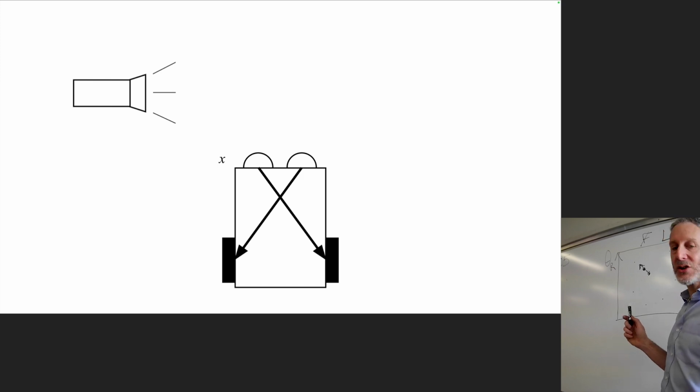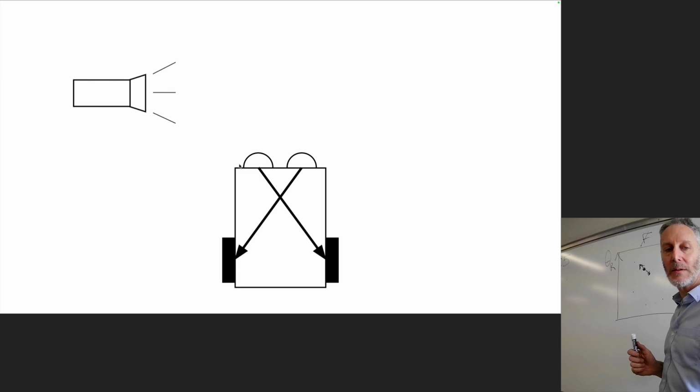Okay, let's imagine in this particular vehicle that we have synaptic weights 1 and 1. Let's assume that we change x. We move the left light sensor a little bit further to the left. How has that changed the behavior of the robot? If this second robot still has the synaptic weights 1 and 1, does this particular robot do a better job at photophilia than this robot?